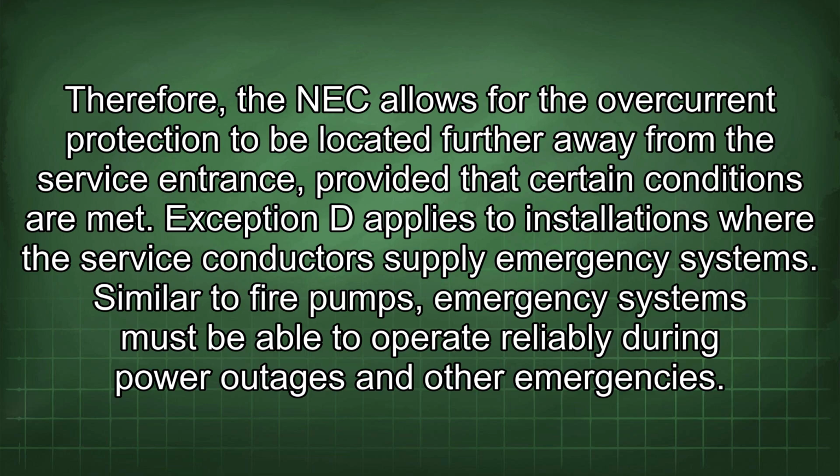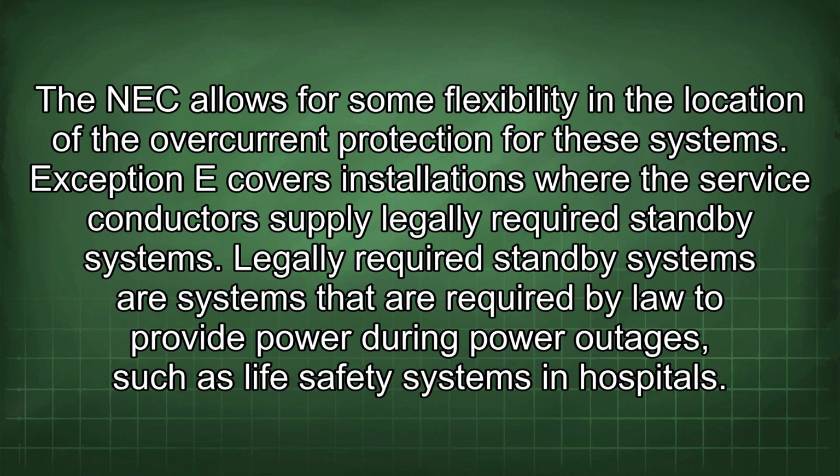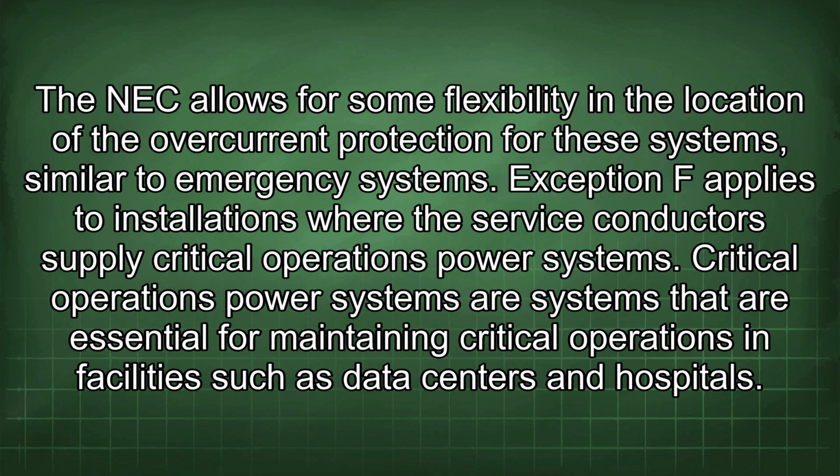Similar to fire pumps, emergency systems must be able to operate reliably during power outages and other emergencies. The NEC allows for some flexibility in the location of the overcurrent protection for these systems. Exception E covers installations where the service conductors supply legally required standby systems. Legally required standby systems are systems that are required by law to provide power during power outages, such as life safety systems in hospitals. The NEC allows for some flexibility in the location of the overcurrent protection for these systems,